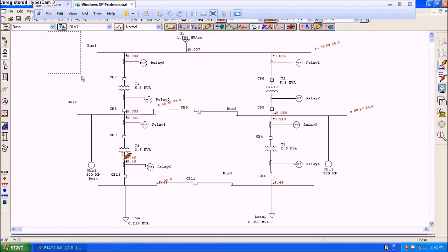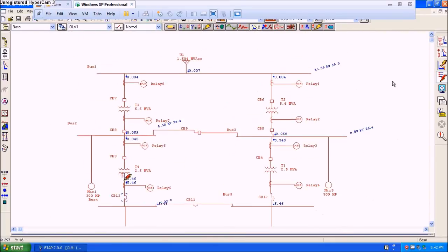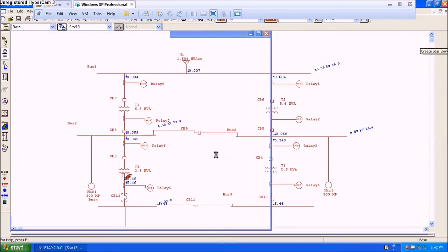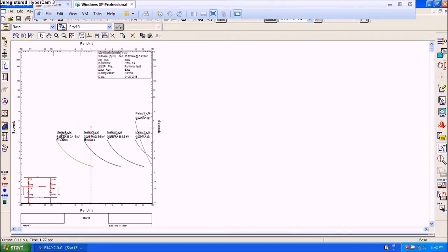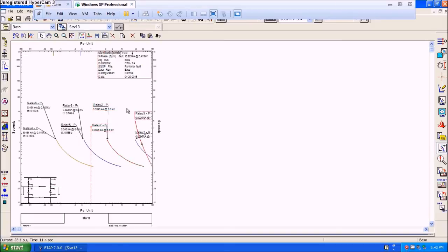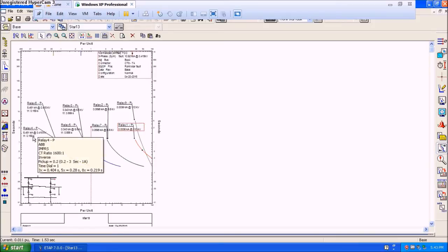Now we will show you this in the circuit. We will explain our concept. So we can bring our circuit from here. You can see the operating times of two relays are the same, which are 6 and 4, and at the same time the time settings of relays 5 and 3 will be the same. We will not consider the relays on the upside, because we have to show the connection between these two relays. Suppose a fault occurs here below relay 6, then relay 6 will operate, then relay 5 will operate.